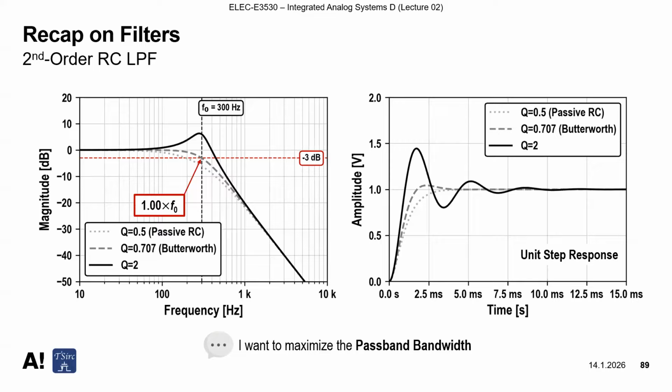When we plug in 3 dB, we find the frequency value that makes the magnitude minus 3 dB, which is 1 times F0. Of course, this is not exactly minus 3 dB, but minus 3.010299, as we did. What about the other case, the passive RC filter?